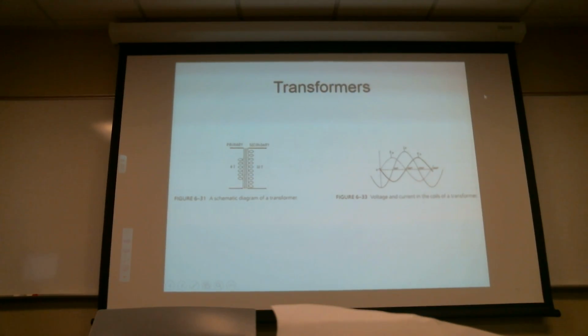How do they sync the phase? Like if you have a solar, right, or a generator system, and you're trying to sync up to AC? Well, first thing you're going to have to do is, because the solar is going to come out at you at DC, you're going to have to put it through an inverter, and then the inverter is going to have to sync itself to existing AC systems. So one of the things it's going to have to do is monitor AC, or it may load shed.